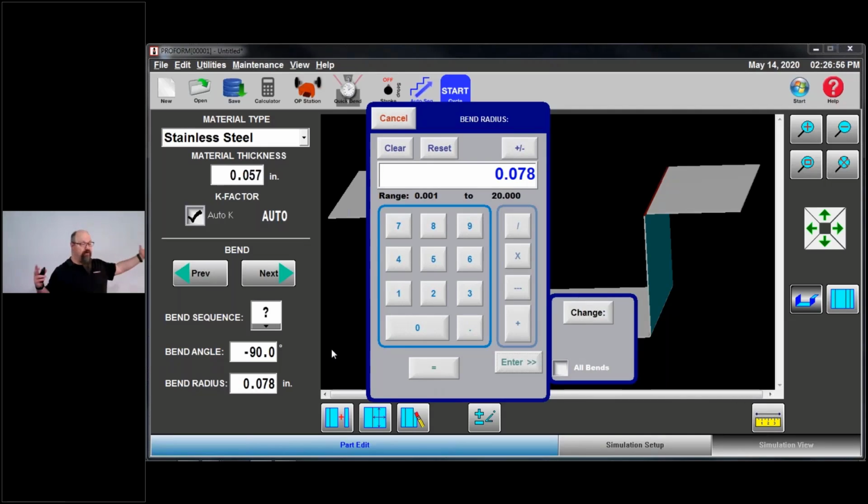And again, there's a whole lot bigger explanation on that I'm not going to go into in this presentation. Just understand we're going to be using a 5/32 value to calculate bend radius. Now, the V that I'm actually going to be using for this is a Wilson lower die, 50022 is the tool number. It's got a 0.404 V opening. So in order to calculate this, I'm going to go 0.404, my V opening on that die that I measured, times 5/32 or 0.156 equals, so that's my bend radius.